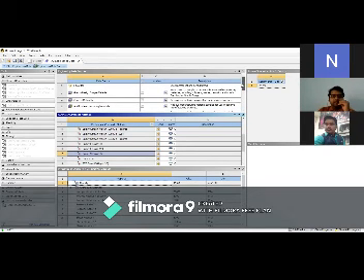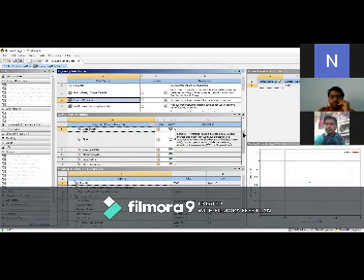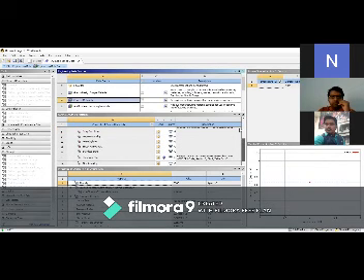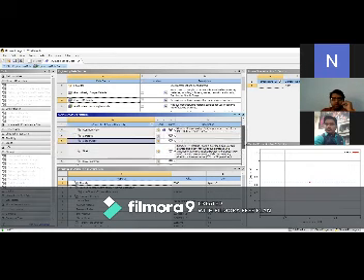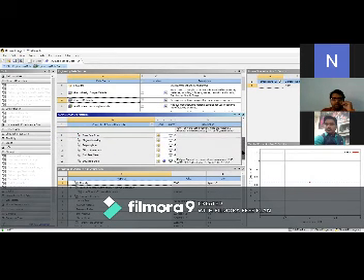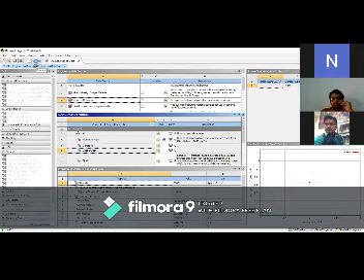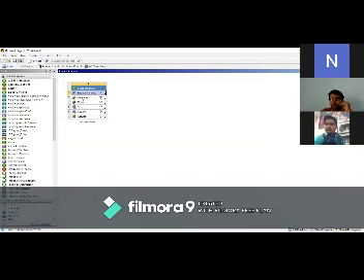Next, we select a different material. Suppose for the piston material, we take the aluminum alloy. So go to aluminum and click on aluminum alloy. Here we take the piston as aluminum alloy or steel. The piston is made of structural steel, which is already set by default. Then go to the project, and right click on the geometry.